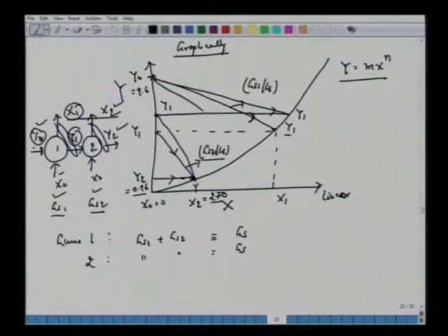Choose another guess here. This is y1 again. This y1 is in equilibrium with x1, new values of x1. So we know now the new y1. Once this y1 is known, we connect with this and we have different values of GS2. So one has to make these guesses and see which way it falls, which number gives you the best or minimum amount of GS min. And if you do this exercise graphically as well, you have to take several of these, and you must be able to convince yourself that you are getting the same numbers.